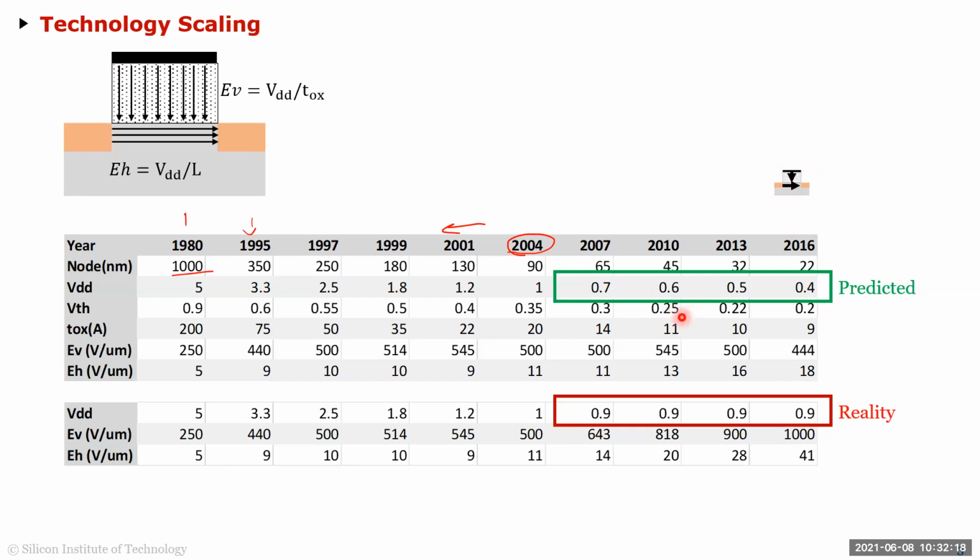with low leakage current, right? The whole idea of going from BJT to CMOS is that when you switch off a transistor, there's no gate current, there is no drain to source current, right? That's the whole idea of going from BJTs to CMOS. But when you go to finer technology and you drive your threshold voltage to, let's say, 0.2, then first of all, you have gate current now, because once you get to this kind of thin oxide, because of quantum tunneling, you actually have gate current. So we have been assuming the gate current is zero. That's not true with these kinds of technologies. Actually, you have finite gate current.